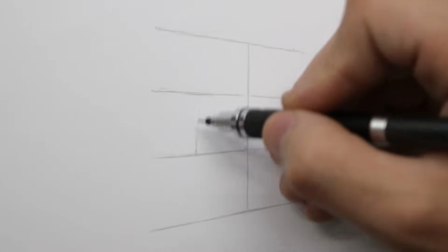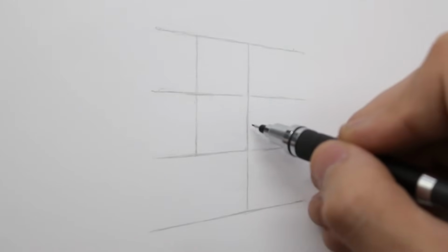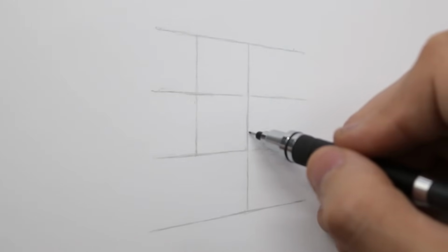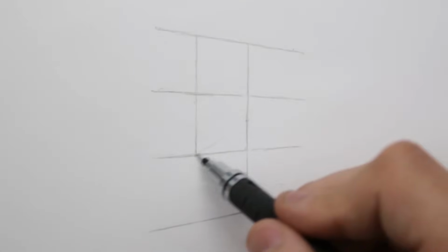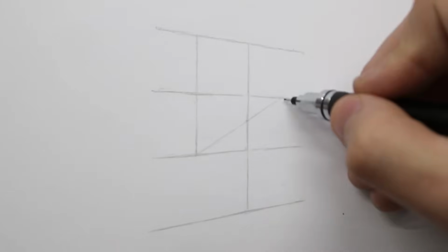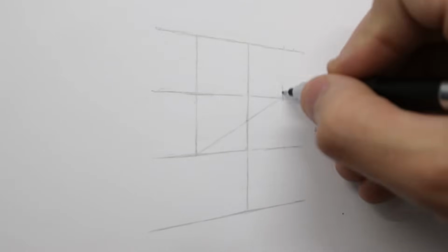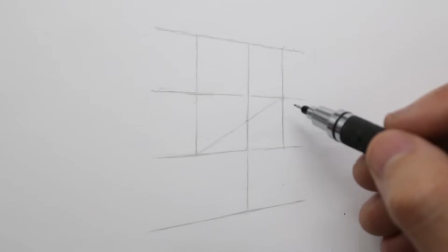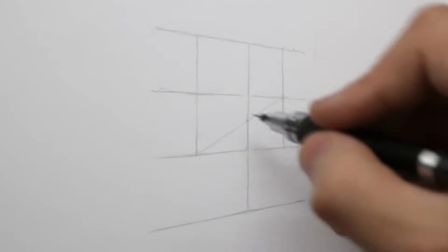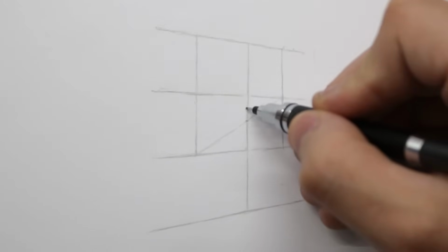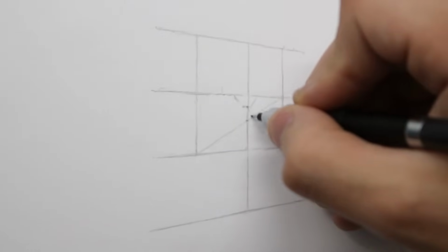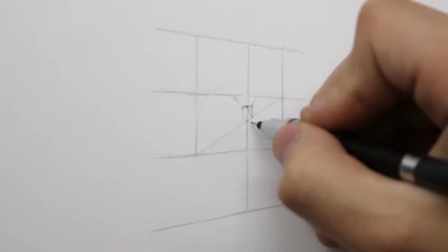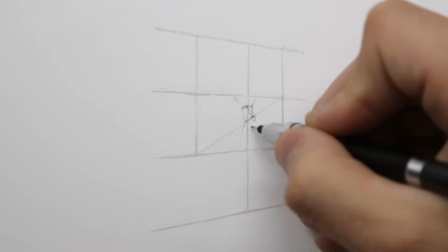I find a centre line and then I find the first section. Now there's going to be a bit of foreshortening here, so to duplicate this section accurately, I bring a line from the bottom corner through the halfway point. Where this line meets the other is where I draw that next section. So now we have this grid in perspective and I make the same divisions. I'm going to construct this the same way as last time, but I have to consider the overall perspective, making sure the features on the frontal plane follow the same convergence.